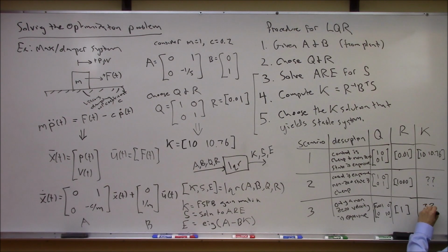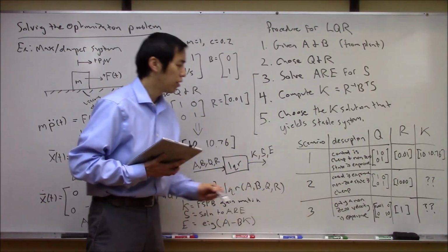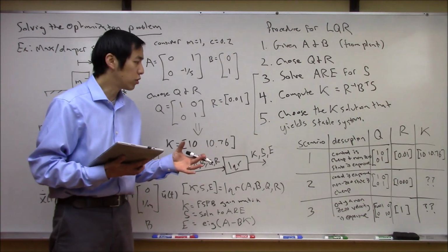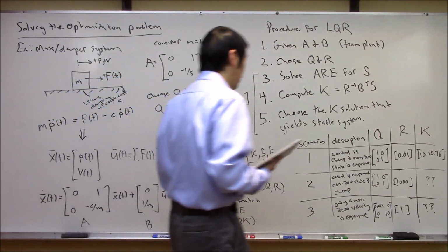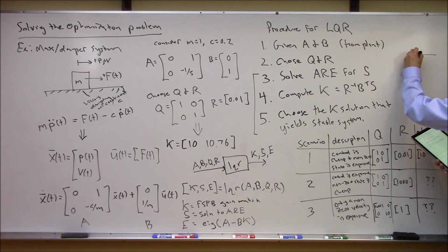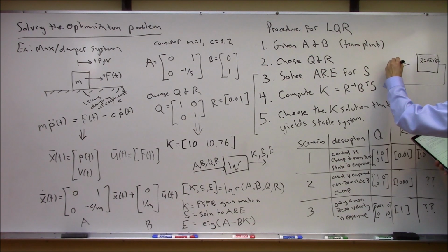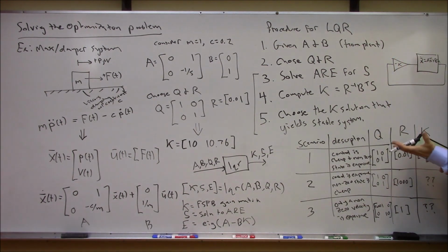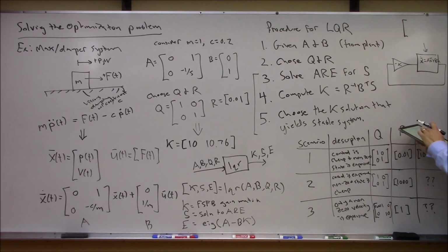All right, so now that we've set this up, we've got all the different Qs and the Rs, let's run over to Matlab. We're just going to call LQR 3 times on each of these scenarios and see what the resulting matrix K is, and then why don't we simulate that using our full state feedback controller. Because we said that once you get this gain matrix K, the optimal thing to do here is to have your plant, your x dot is equal to Ax plus Bu, and we're just going to wrap this back through a minus K. And let's use some initial conditions. I don't know, maybe in here, let's use initial conditions of, what did I end up using here?